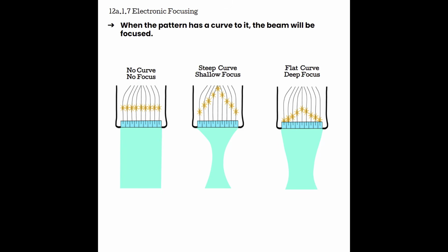We have to have multiple crystals, each consisting of their own channel, all capable of receiving multiple types of electronic patterns to excite the PZT material in a particular way. When we are using electronic focusing, the machine is capable then of not only multi-focus, but also having adjustable focus. So the biggest part to remember about electronic focusing is how the pattern of the voltages coming down the wires